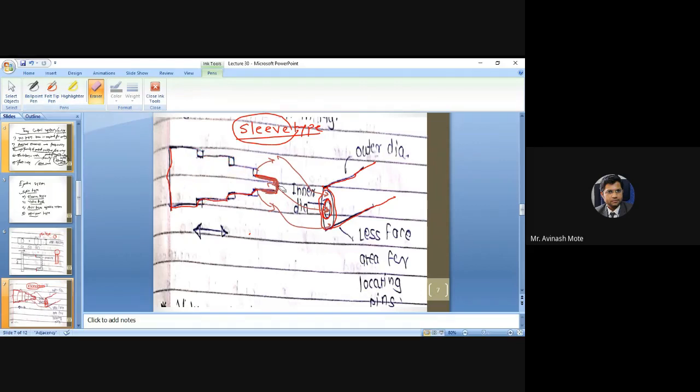Currently we are using only this surface. Getting it? Only this surface, the first one. So this will go inside the cavity, inside the hollow area, and this one will rest on these two side surfaces. And you can easily eject the product from the cavity.